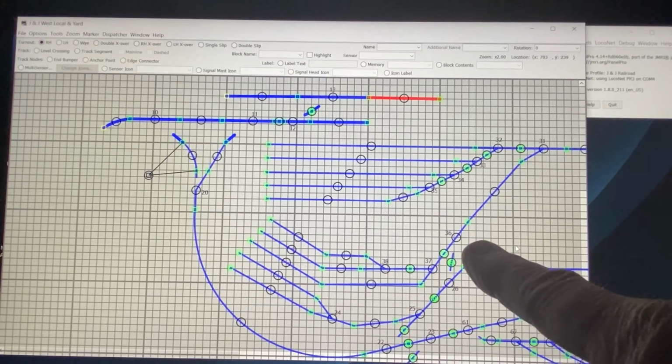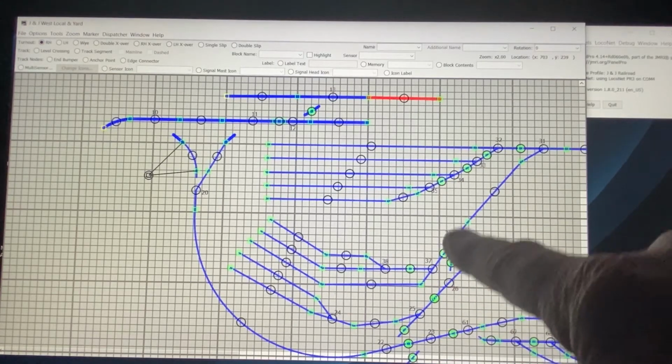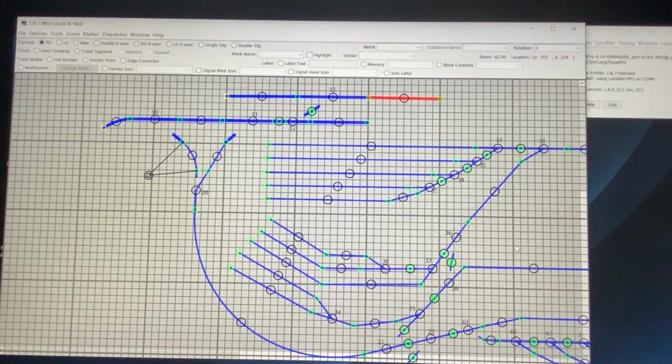and the diagram indicates correctly only because JMRI assumes that since I clicked on that turnout, I wanted those turnouts to go to the closed position, and therefore it assumes that that's the position that they're in. JMRI really does not know where they are. It sent the signal to send them there, and in fact they are in that position. But JMRI really doesn't know that because it has no feedback.